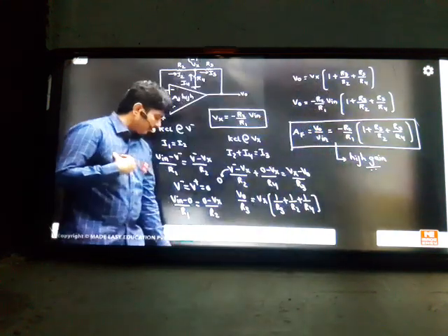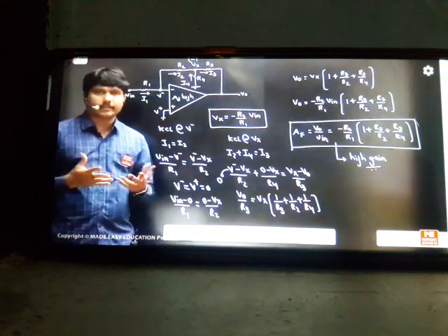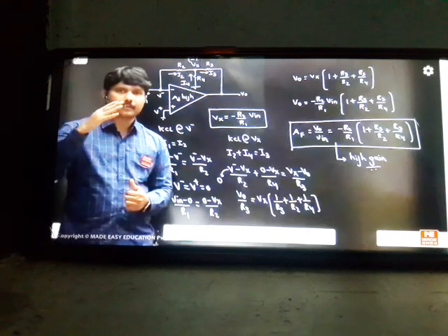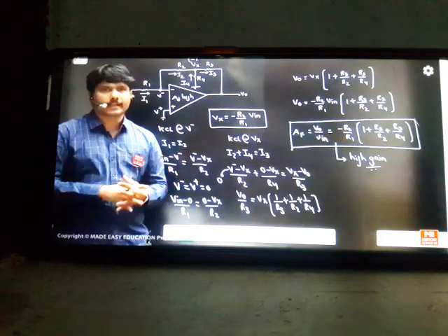We can increase the gain whenever you have very small inputs, like 1 millivolt. At that time the situation is we need a gain of 10 power 3, and also the system will be linear for you. At that time the gain has to increase. In negative feedback, the RF resistors we cannot make close to 1 mega ohm. So to overcome that, I have used the T network technique. Okay?